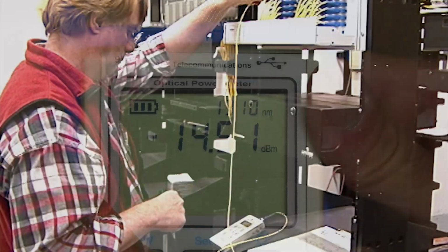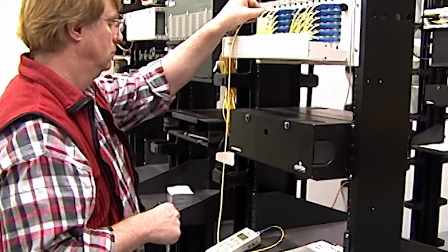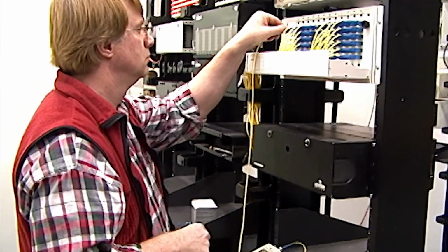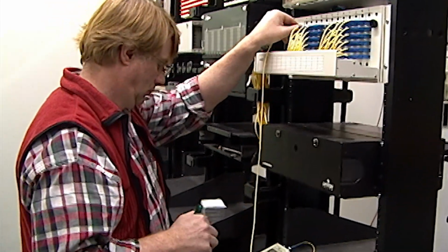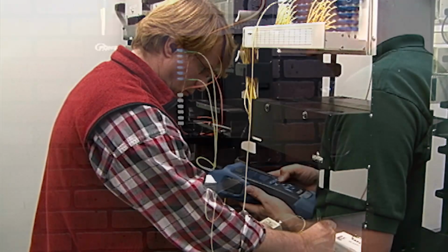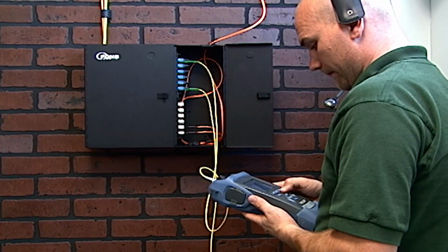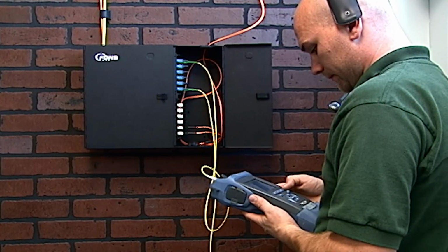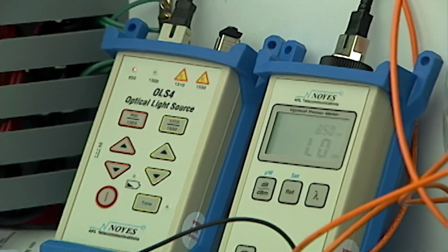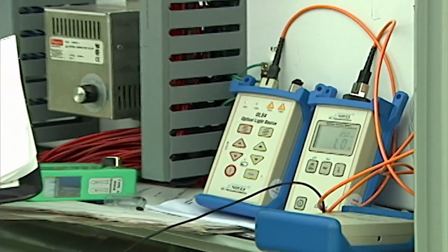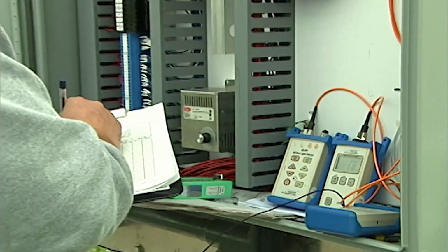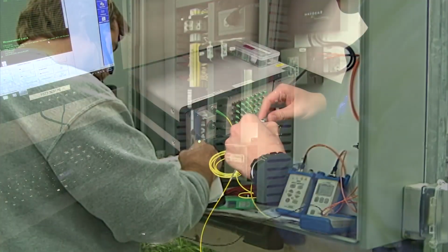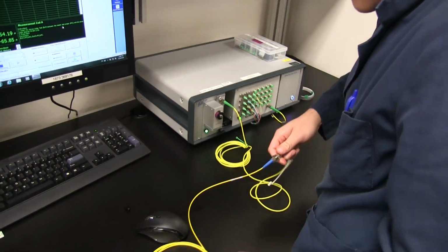Optical loss testing must be performed when a fiber system is first installed to verify fiber continuity, validate correct polarity, and certify that the attenuation of each fiber meets design specifications. Testing is then performed periodically as the system ages or is modified to verify that attenuation stays within tolerance. It is important that all tests be fully documented so that future tests can be quickly compared to previous values. Any increases in attenuation over time may be a sign of trouble that should be addressed before it causes a system failure. Unfortunately, optical loss testing can tell us nothing about reflections present in the system.